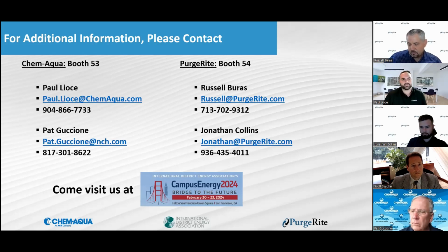The other side is what Russ was saying, that you're not doing a complete system turnover one time, right? If you think of it kind of like a pool, you might have a 100,000 gallon pool, but you're only filtering 20% of that at a time. So it's very similar to that. When you're doing those continuous bleed and feeds, you're not turning that system over at a 1-to-1 rate.